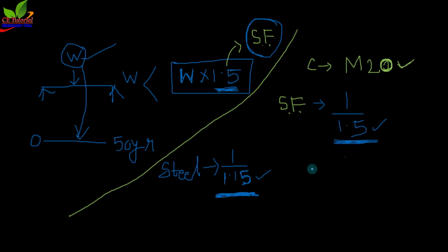Yes, not only temperature, the concrete is sometimes made by unskilled labor. So there are various factors which will affect the strength of the concrete: temperature, water cement ratio, the quantity of cement, quantity of aggregate, the properties of aggregate, all those things will come.